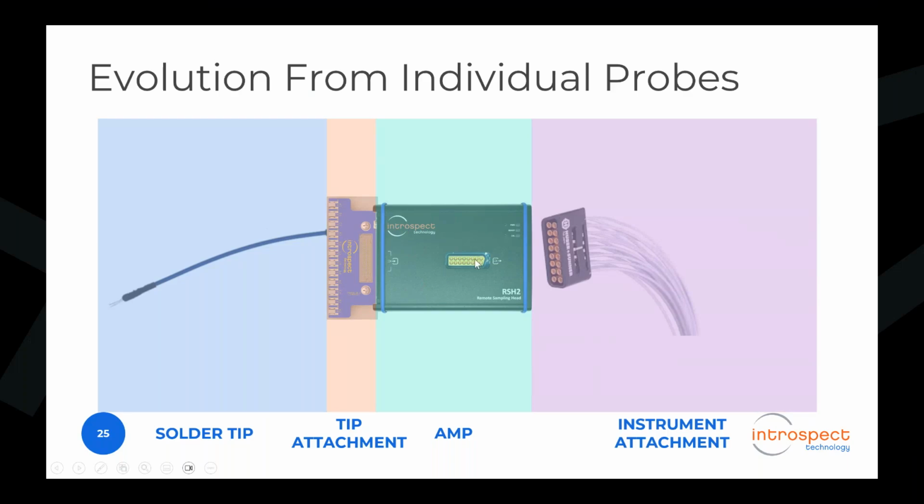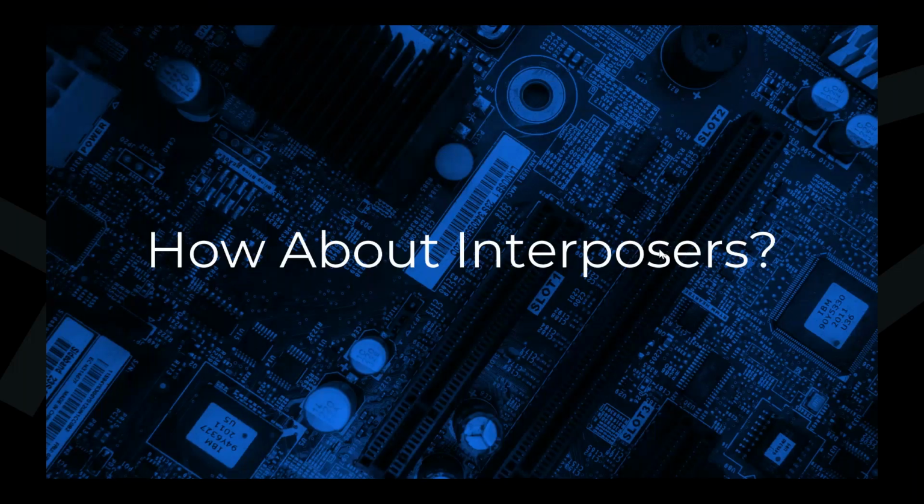And then since there are 12 coaxial cables coming out of the probes, we have decided to go with a multi-coax solution like the one we're showing here, where you have 12 outputs going to the scope or to the protocol analyzer. So the point is, this is really a conventional oscilloscope probe. You can literally take any one of these cables and connect them to the scope and you'll see your signals. But we've compacted the form factor so that we can measure more signals simultaneously and connect them to a protocol analyzer.